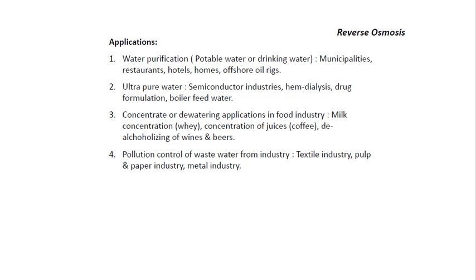Next is for concentrating different materials in the food industry, as well as in the biotechnology industry. Basically the reverse osmosis process is used in the food industry for concentration of milk, juices, coffee, as well as for de-alcoholization of wines and beer. For making constant concentrations of alcohol in wine and beer, we can also use